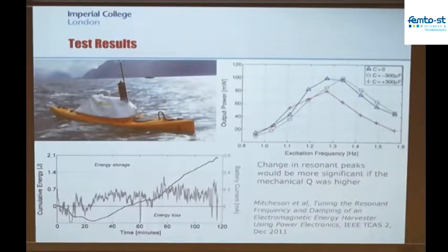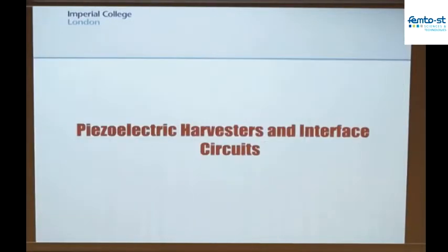So we were able to add a positive capacitance to the system and decrease the resonant frequency a bit, or add a negative capacitance and increase the resonant frequency a bit. It's around a 10% change in resonant frequency here, which doesn't look like much when you're working at just 1 or 2 hertz. But if we can get a 10% change as we move into the kilohertz range, maybe that's quite a useful thing to be able to do in terms of tuning the behavior of this device.